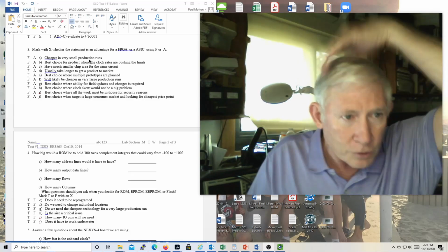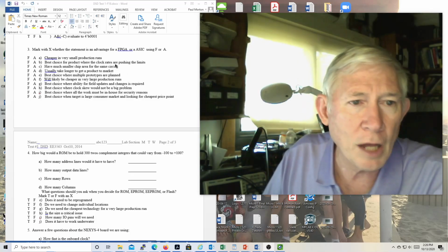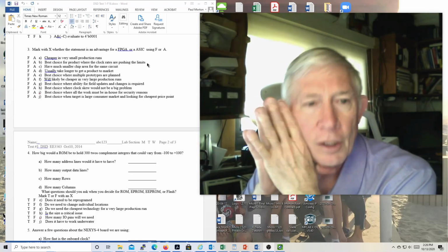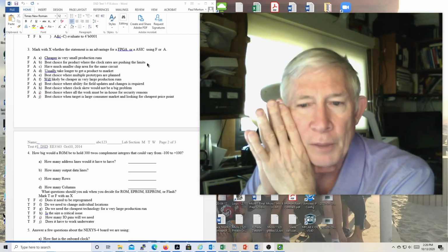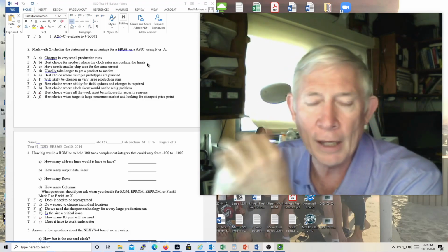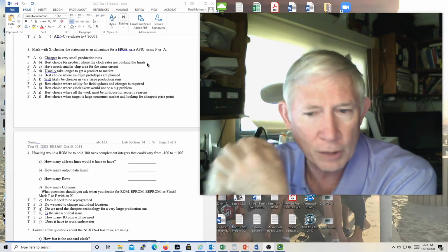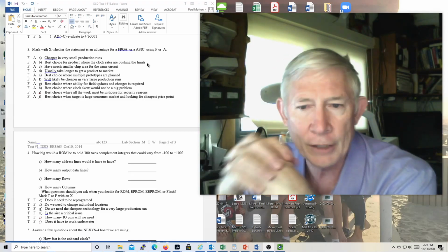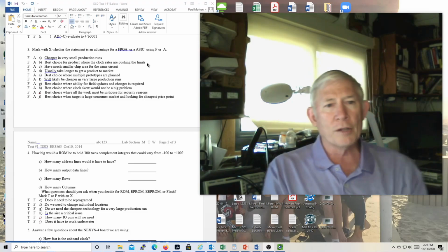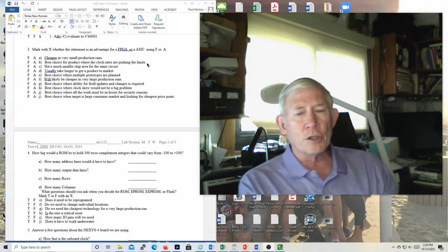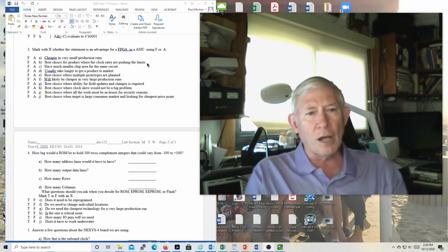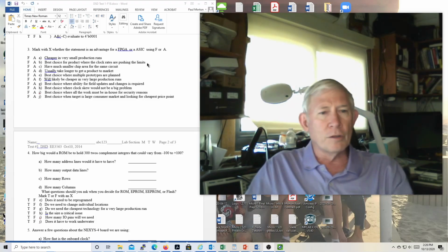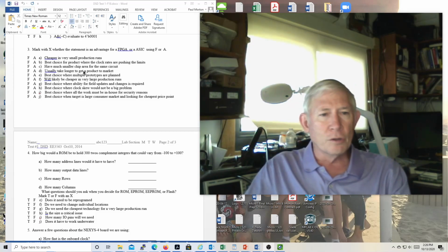All right, best choice for product where the clock rates are pushing the limits. If you really have to push the limits in clock rates, then you probably do want to avoid an FPGA because the routing can be quite complicated and can screw up your timing since you're typically running your signals around a big interconnect matrix. Whereas in a dedicated chip, you're going to control the actual routing of every line, or at least you can, and you need to, then you can push the timing to the limits.